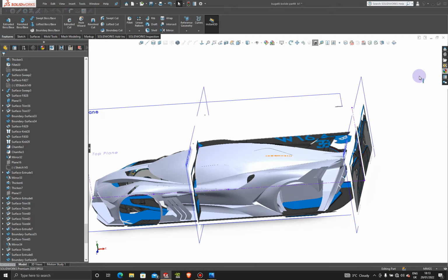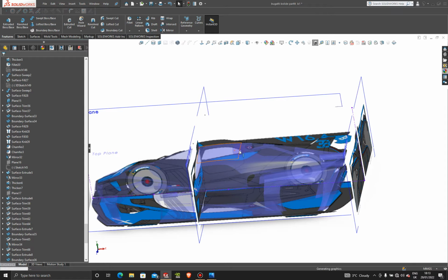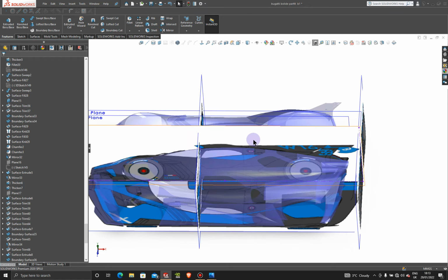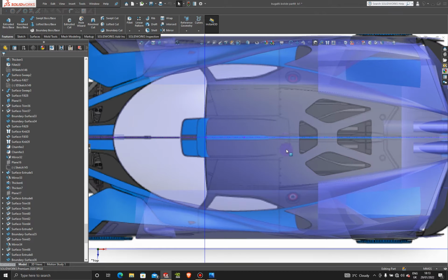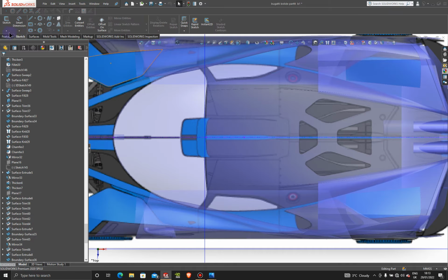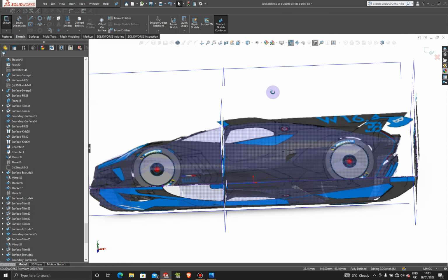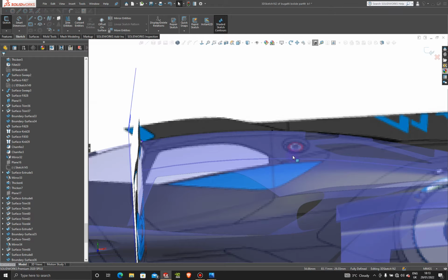And then let's go ahead and add back our glass appearance again. And let's jump to the top. Okay, and let's go to 3D sketch and 3D point. We want to drop that point right over here. And let's just make sure that point is right on the top of the surface, which it is.